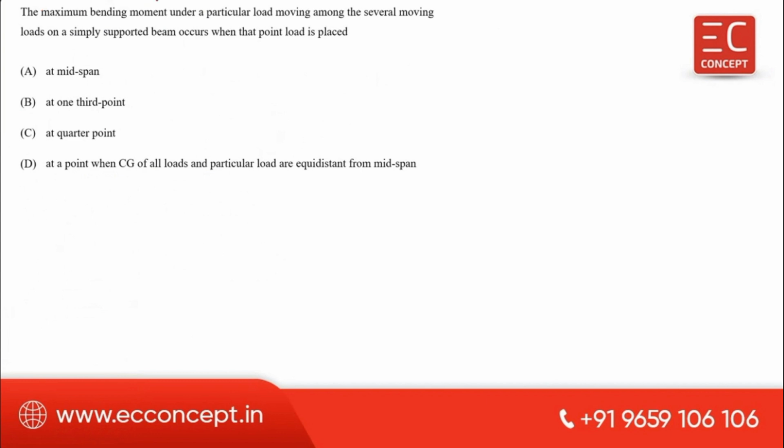The maximum bending moment under a particular load moving among the several moving loads on a simply supported beam occurs when that point load is placed. Answer is this one: at a point when the CG of all loads and particular load are equidistant from the midpoint. For example, let me explain this.